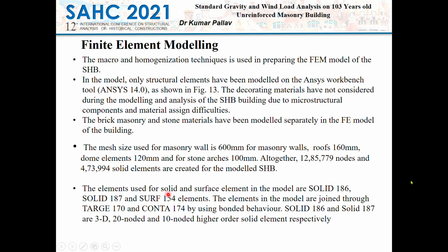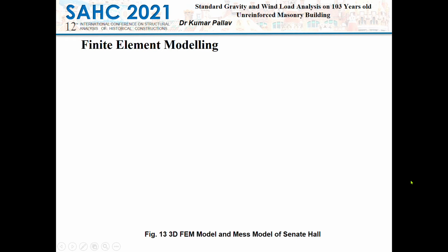The elements used for the solid and surface in the model are SOLID186 and SOLID187 and SURF154. Further, the elements used while we join them are TARGE170 and CONTA174 using bonded behavior. So these are the properties which you can refer to in the ANSYS library, and you will see they are quite good, you can say, in order to predict various behavior of the structures. So we prepared a finite element model, and